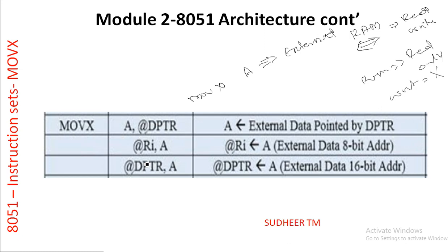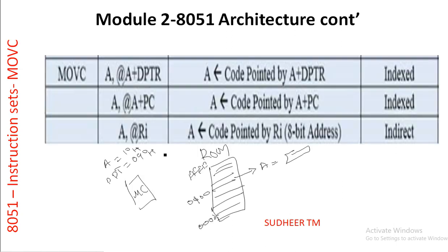So at the location DPTR also we can write, but MOV @A+DPTR comma A is invalid, because what I mean by this instruction is to copy the accumulator to the location pointed by this location. Understood? But this belongs to ROM. Writing to ROM from the program is not possible. So they may ask you MOV @A+DPTR comma A, what is the mistake here?